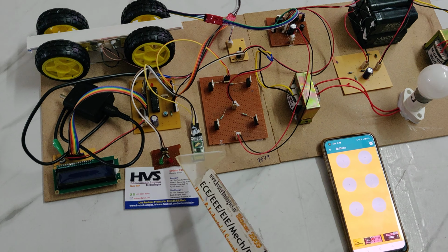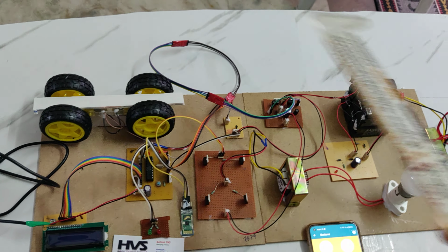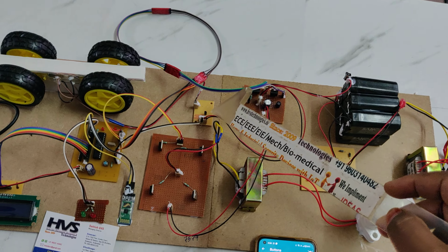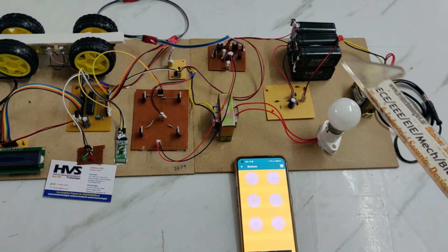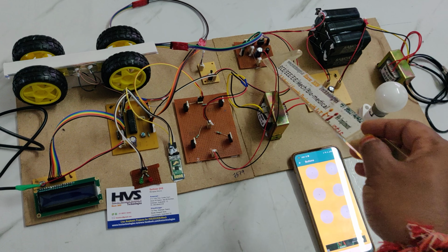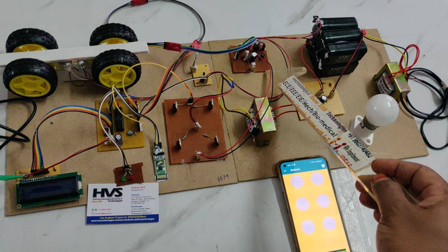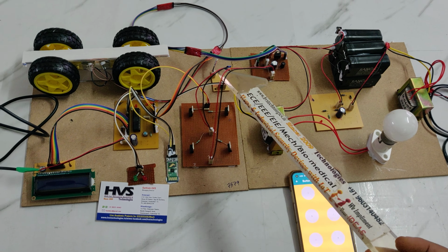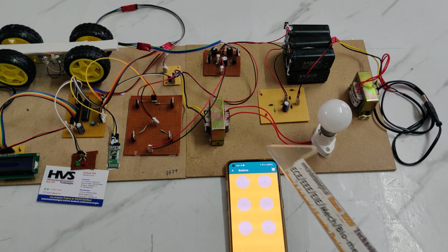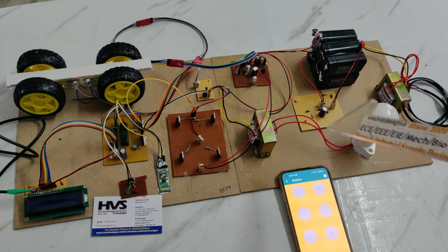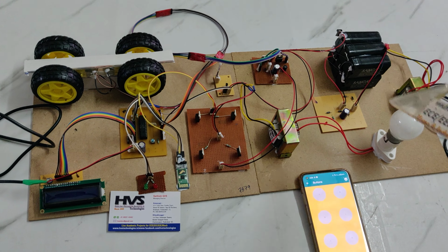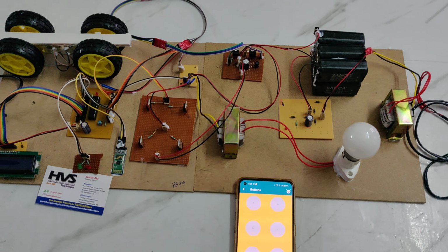Whenever we are controlling grid to vehicle, meaning DC to DC conversion, this transistor is on to control the vehicle unit. When we are doing DC to AC for the grid, meaning vehicle to grid, this will be off and provide the same power supply with the help of this H-bridge. The output of this DC to DC converter goes to the H-bridge, and from there the H-bridge provides 12 volts AC, which is stepped up to 230 volts AC with the help of this step up transformer. And this one is a step down transformer, used for grid to vehicle and vehicle to grid. Let us check the demonstration.